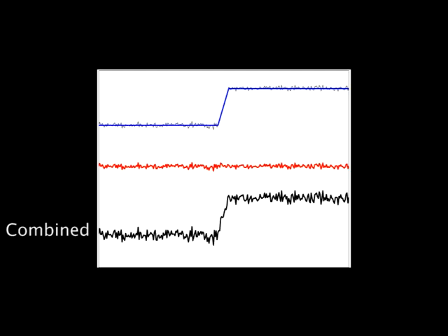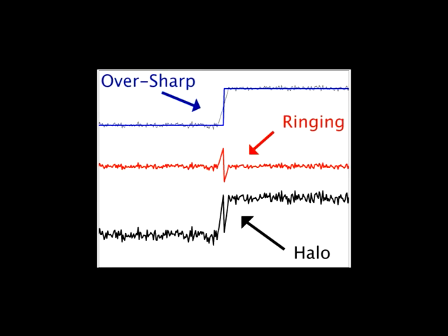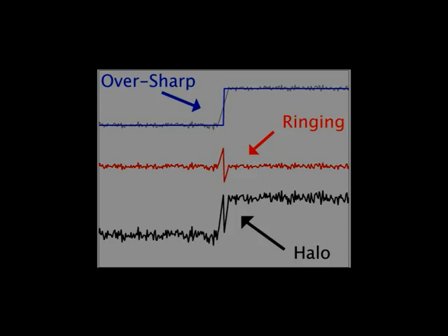By smoothing a signal, one can extract the details at a given scale, which can then be manipulated and recombined with the base to yield the result. When performing the smoothing, it is important to avoid blurring of strong edges, since this introduces ringing into the detail layer and may result in halos once the base and the detail are recombined. Over-sharpening of strong edges may also cause artifacts.